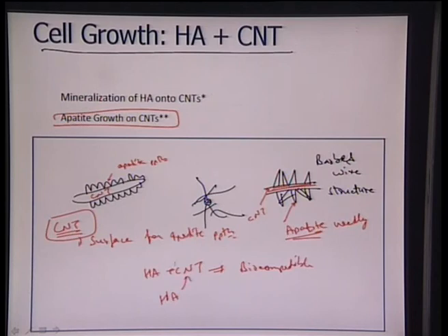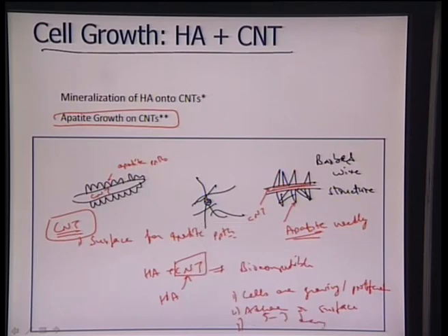So CNT itself is not inducing any toxic effects, because we are seeing that cells are growing and proliferating. They are able to adhere onto the surface, and they are being retained even after a couple of days. Even after around 5 to 7 days, we see that the cells are there on the surface, and we are seeing this apatite precipitation onto the CNT surface, which means that CNT itself is not really toxic, and hydroxyapatite CNT is coming out to be a much superior material with enhanced mechanical properties and with enhanced biological properties as well.